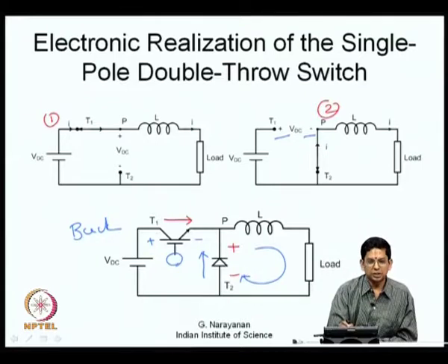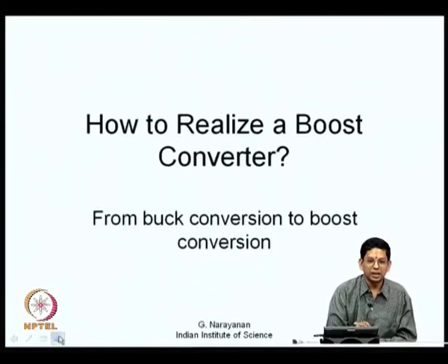So, this part, the single pole double throw switch, is capable of giving you a certain average voltage. The average voltage at P is lower than VDC, and this average voltage is basically the duty ratio times the input voltage. Now, the voltage at P not only has an average, it also has a certain ripple, and that is what actually gets filtered out using either an inductive filter, an inductance, or an LC, and that can be effectively filtered now. So, this overall is a buck converter now.